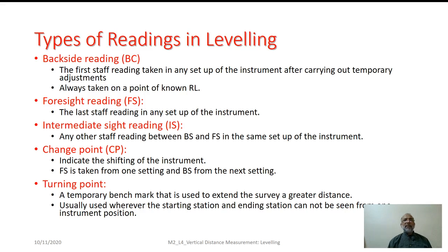After carrying out the temporary adjustments, after leveling the equipment, after focusing the eyepiece and objective glass, we can take the reading on a point of known elevation, and such reading is termed as backsight reading. Please excuse me, these should be backsight, SIGHT.